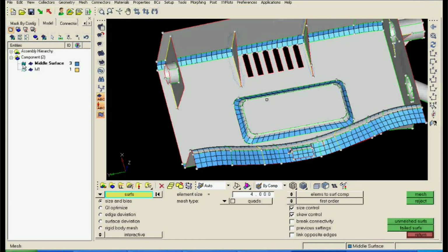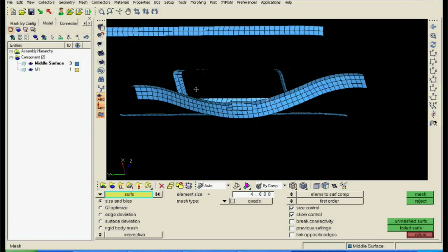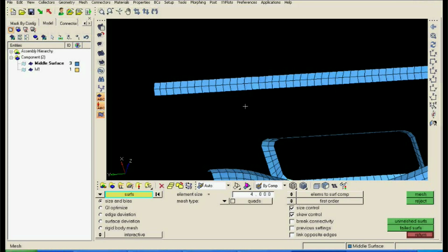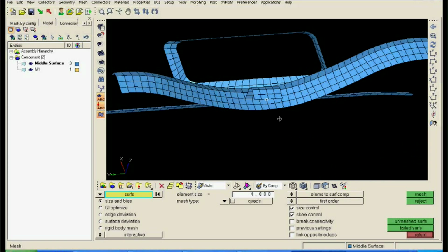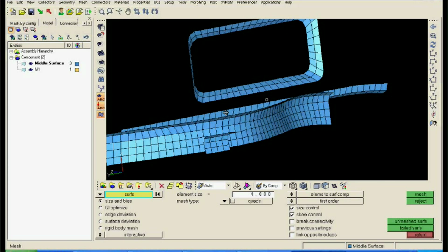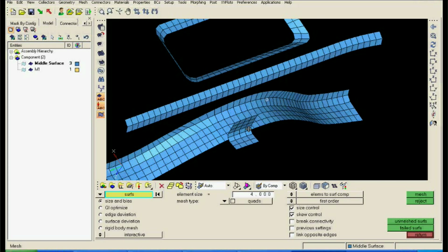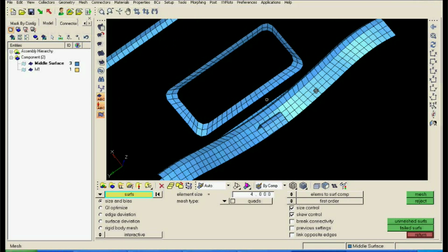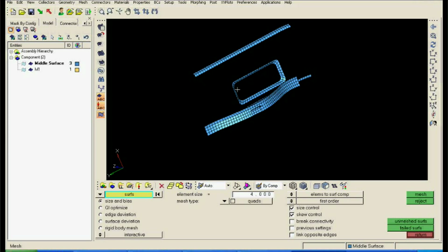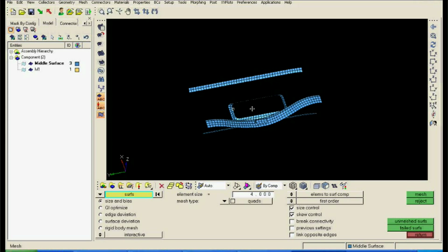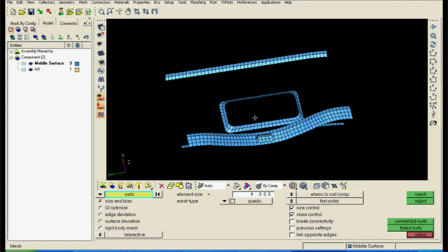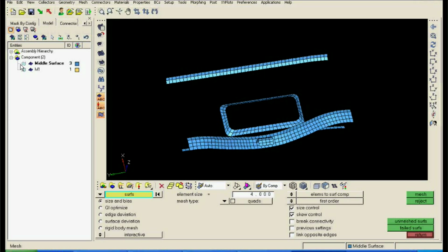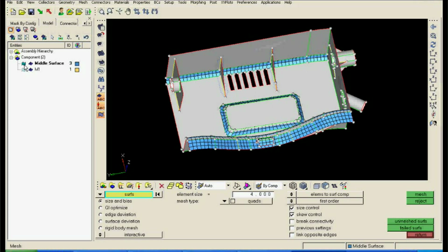So in the areas where it is possible to have such a nice mesh element, you have to try this. Again, this will depend on how big the model is, how many elements you can afford, and things like that. But just as of now, for practice, you should do this more often: in the areas where it is possible, try to keep a nice mapped mesh and practice them.